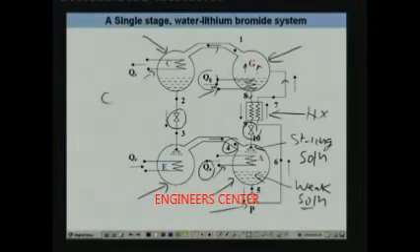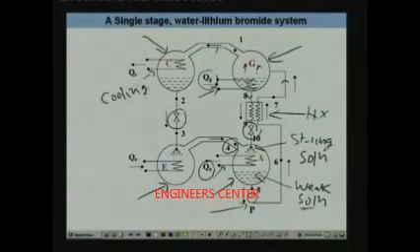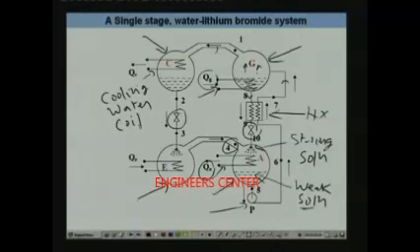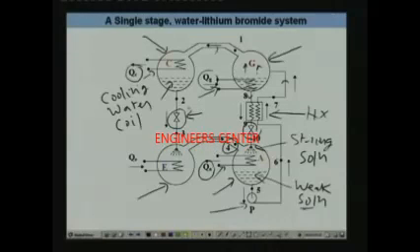In the condenser, the vapor comes in contact with the cooling water coils. This is the cooling water coil. And the vapor condenses. Since condensation is again an exothermic process, here heat has to be taken out. So the cooling water takes the heat of condensation out of the system. So what you have here is pure water in liquid form. This is still at high pressure, so the pressure has got to be reduced. So this water flows through this refrigerant expansion valve, where it undergoes pressure drop,